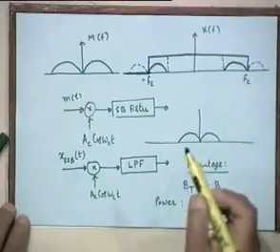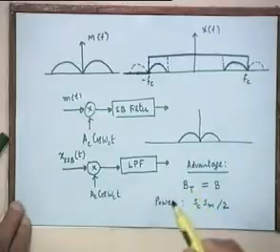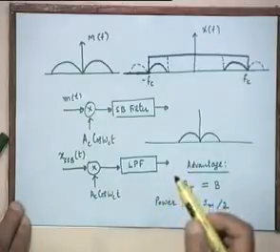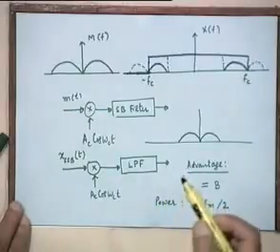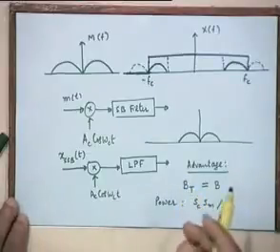And designing high Q filters, high quality factor tuned filters using conventional passive components like inductors and capacitors is extremely difficult, right? They would be typically very large order filters, and remember, no matter what you do, how ideally you construct your inductors and capacitors, there will be losses, right?